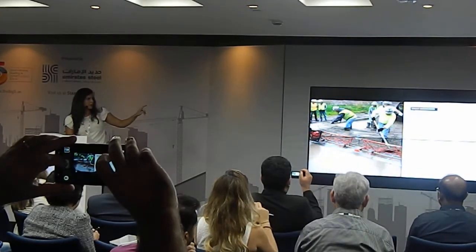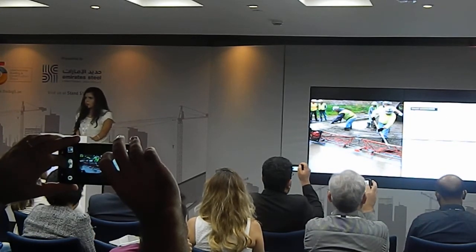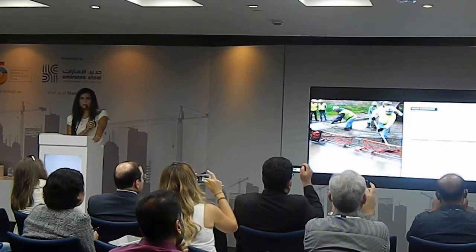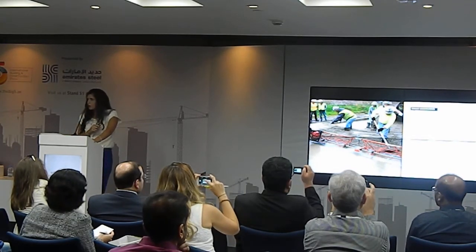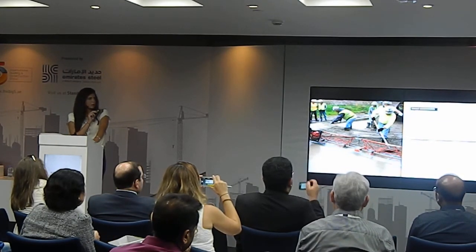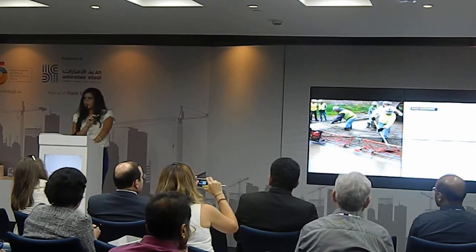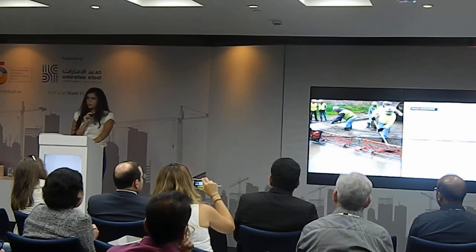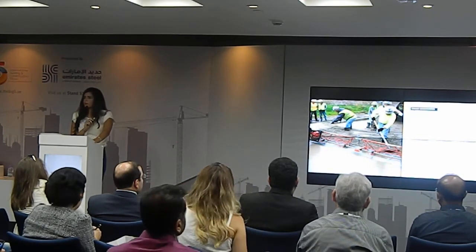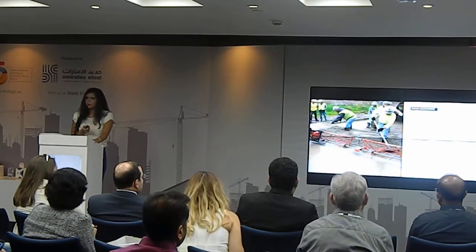Yeah. Green cement. If you're looking at structure, they're saying that they've created this green cement. This is something that the biomunicipality is actually encouraging the use of. So what they're trying to do is create a cementitious material that uses around 50% less carbon emissions than the usual Portland cement, and it uses around 50% less water. So again, this is something that is already in the market and we could start utilizing.